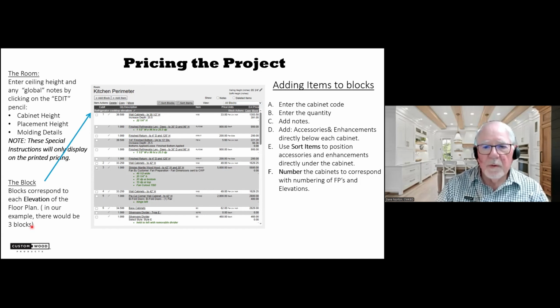And again, we're numbering cabinets. You only want to number the cabinet. You do that by clicking the edit pencil. And what it will do for you is it'll put lines between cabinetry. And so all of these modifications on the refrigerator enclosure are visually tied to that cabinet.